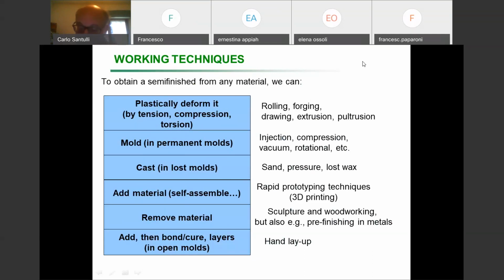In the case that metals need particular characteristics against wear, for example, you need to feed into metal some ceramic particles, like a typical metal matrix composite with aluminum matrix and alumina particles.